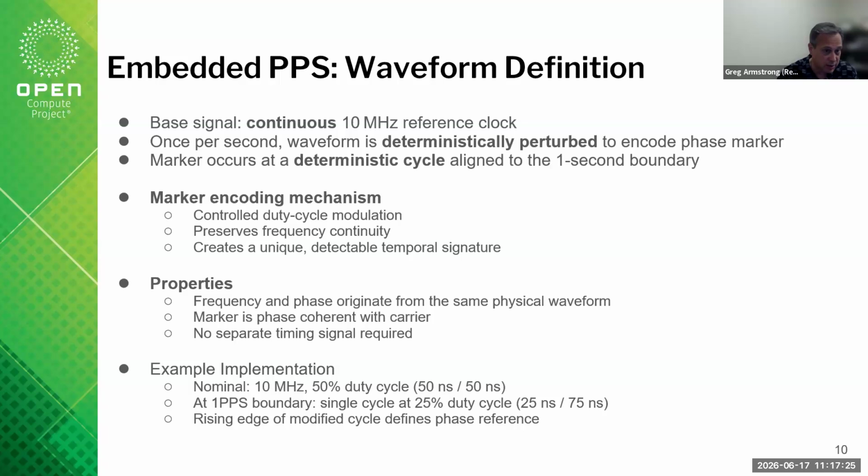So historically, what that concept means for most people is what they call pulse width modulation. They are effectively manipulating the duty cycle of the clock to represent some symbol, like a 1 or a 0, by manipulating that pulse to maybe be a quarter of the width or maybe 3/4 of the width to represent different things. And so by doing that, you can create a marker within a standard clocking signal, but it doesn't actually disturb the frequency clock itself.